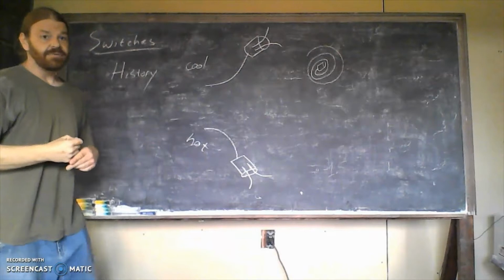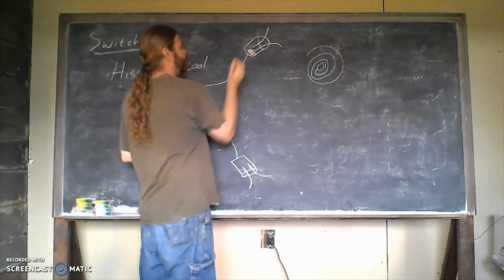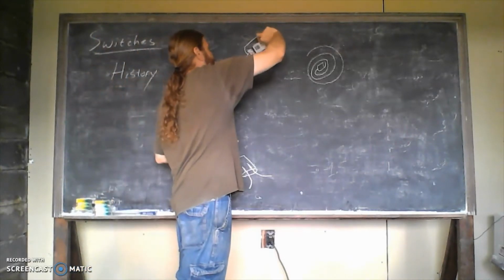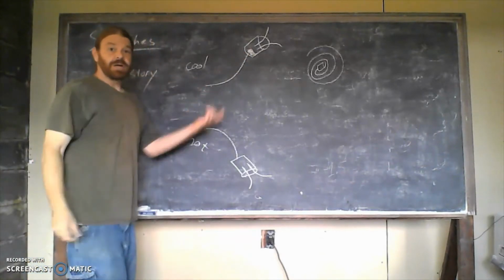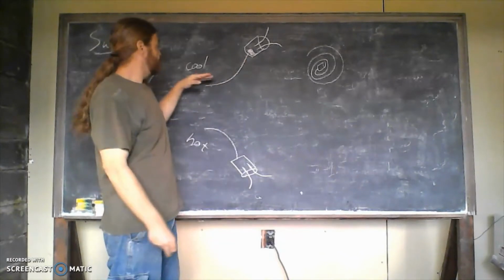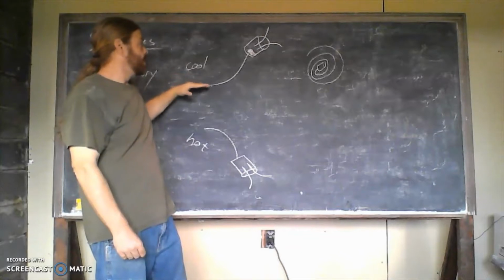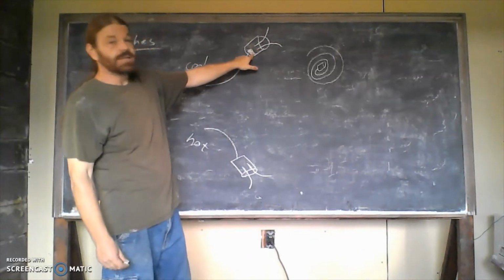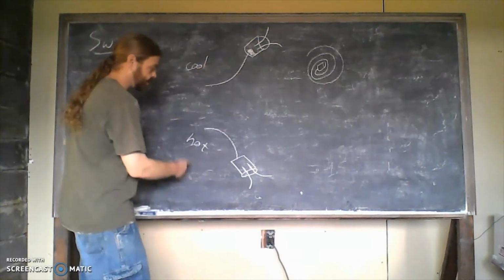And inside of that glass tube, there would be a little bit of mercury, a liquid metal. So when, like I drew the picture here, it's cooled down, that bimetallic strip curves up, the liquid runs to the bottom, and those lines aren't connected anymore.